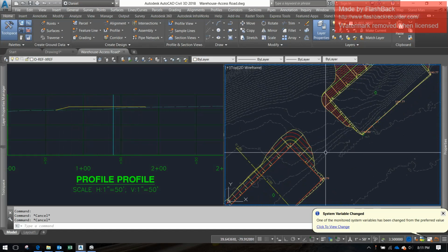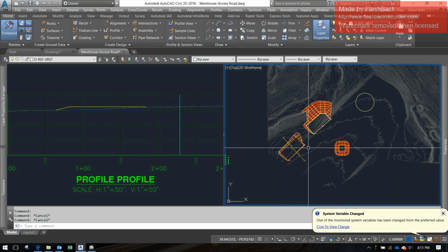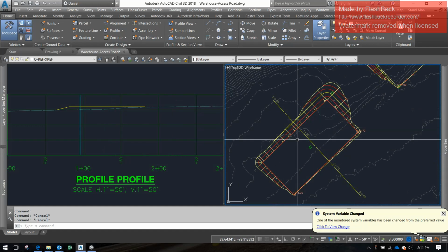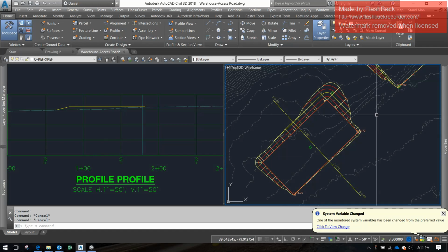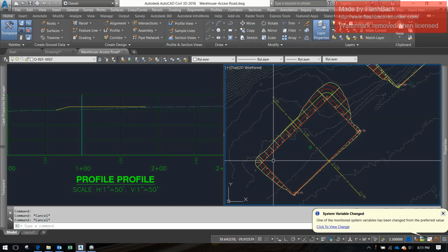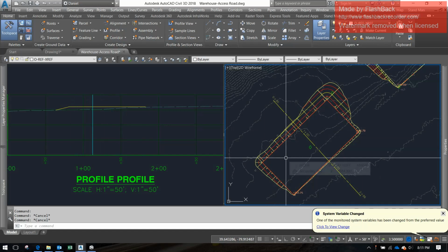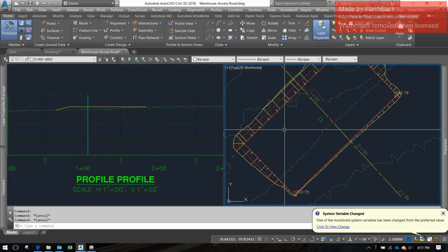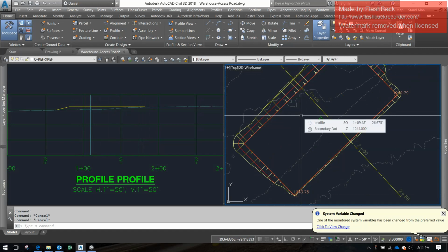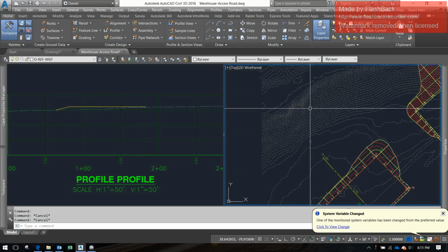So we're going to say, I'm trying to think of ways to put this that's realistic too, like an airport or something like that. We're going to say this is a fueling pad, right? So they're going to put some gas tanks up here, a little fueling station for trucks to come by. Fueling stations typically need to have what's called secondary containment, which just refers to if a fuel tank was to have a leak or a spill up here and it were to rupture, the fuel and the liquids wouldn't just spill over the edge and run on down the hill to the nearest receiving stream.